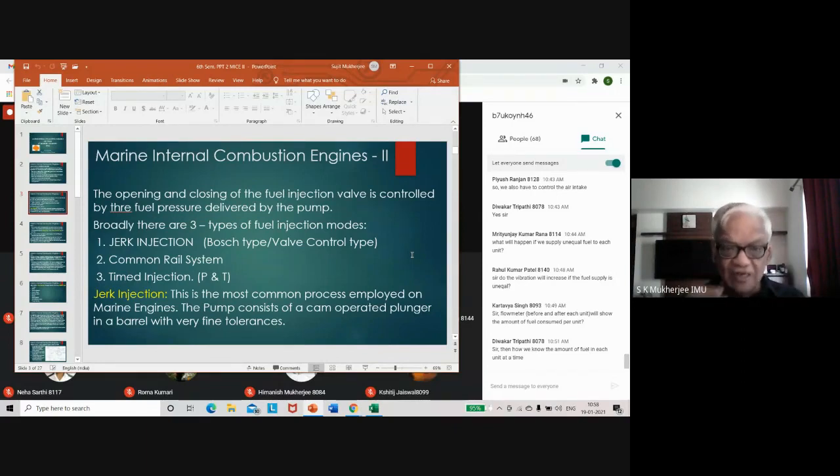The term solid over here is a misnomer. It is used because liquid is incompressible. So a solid injection means when the liquid is compressed, that liquid instantaneously delivers. There is no scope of compression. If the pipe had air in it, you can compress and nothing will be delivered from the other end. So that is why we need to prime the lines.